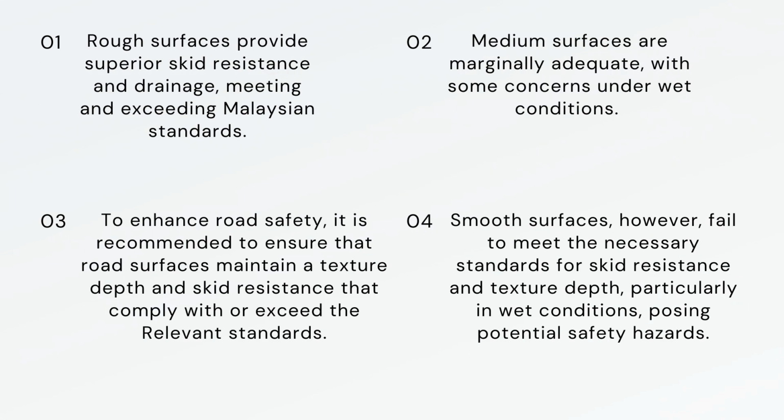The results demonstrate that surface texture significantly impacts skid resistance and water drainage. Rough surfaces provide superior skid resistance and drainage, meeting and exceeding Malaysian standards. Medium surfaces are marginally adequate, with some concerns under wet conditions. Smooth surfaces, however, fail to meet the necessary standards for skid resistance and texture depth, particularly in wet conditions, posing